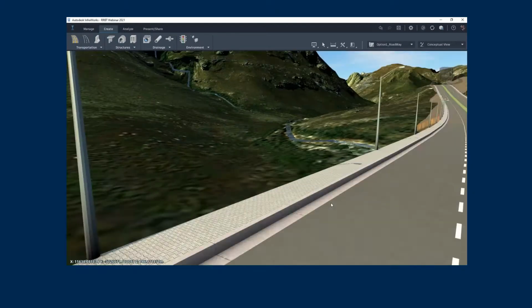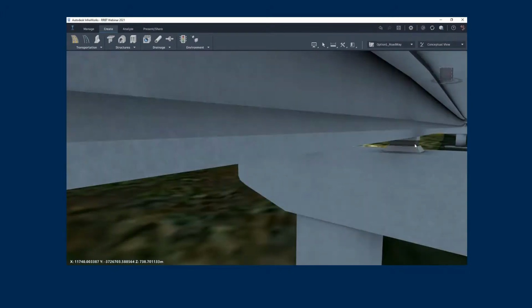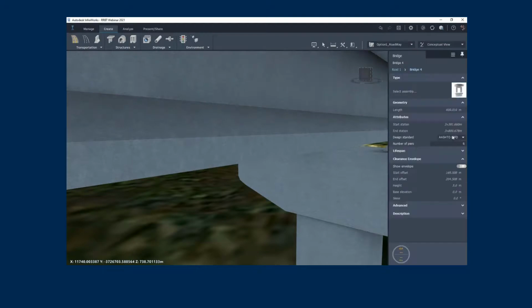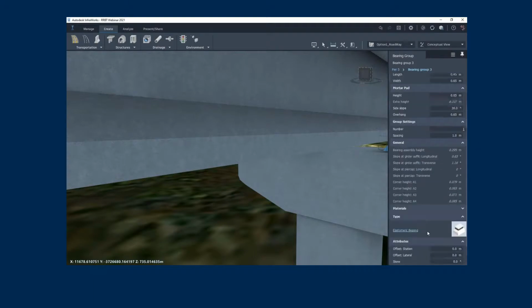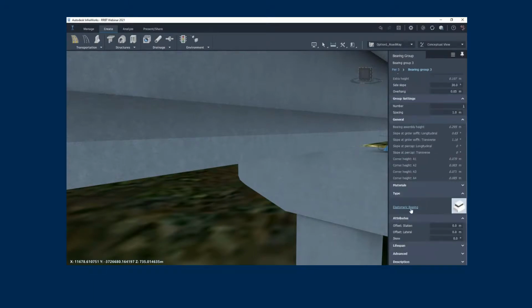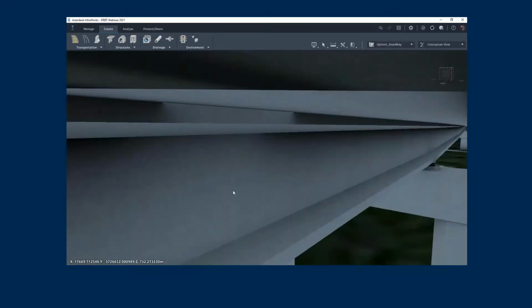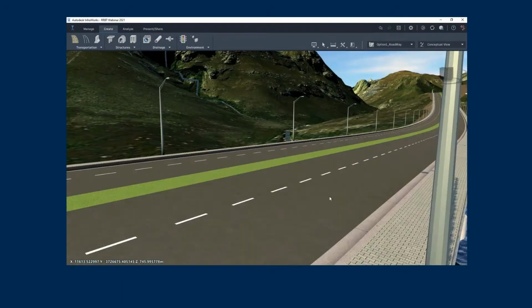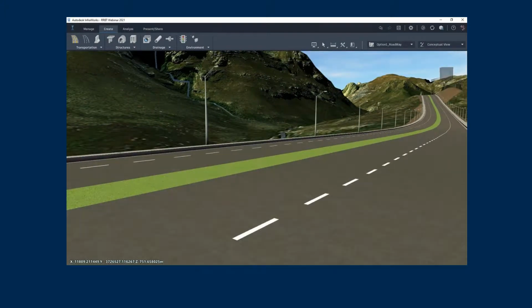As you can see, it looks pretty good. We can also customize these. You can customize each and every element. For example, I clicked on the bridge bearings. If I select that, all of the metadata associated with it can be edited accordingly. As you can see, it is an elastomeric bearing, and I can go and change it, or I could create my own custom bearings and incorporate them if needed. The same applies to all of the elements attached to the parametric bridge. And this is how you would do it.